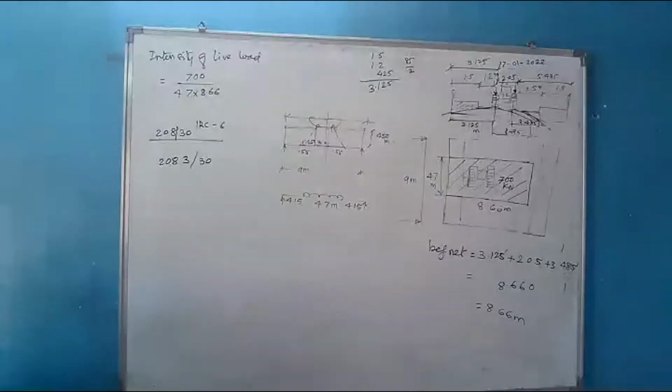208.2 is applicable for class A or class B loading. 208.3 is applicable for class A loading and 7TR loading. In it, two parts, A and B, are given. Part A when the span is less than 9 meter. Part B when the span is 9 meter or more. Okay, ours is 9 meter or more. There we will see reinforced concrete bridge, right, it is equally applicable for pre-stressed bridge. Then in that also two parts are given, tracked vehicle and wheeled vehicle.